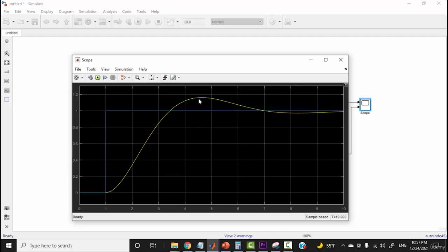So if the desired speed is 100 RPM, so when we run our system, the speed of the motor starts from 0 and then goes up, as we see here, and at this point then the speed of the motor is 100 because it is equal to the input, it is equal to the reference, and then it goes up again in this overshoot, until the speed becomes, for example, 120 RPM, and then it goes down and goes up until at the steady state it will be equal to the reference input. So this is how you understand the control system classes.